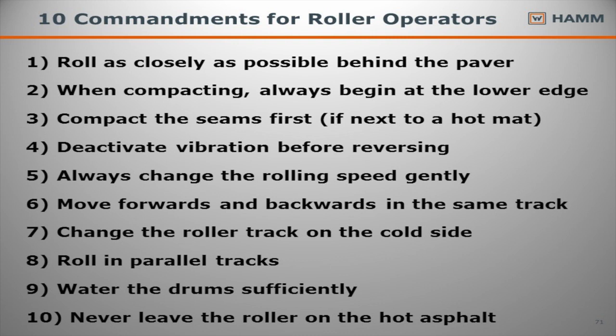Water the drums sufficiently. I tell everybody we don't need to have Niagara Falls coming off that drum scraper. You only need enough moisture on the drum to keep it from picking anything up. You want to spend more time behind the paver and less time at the water truck.